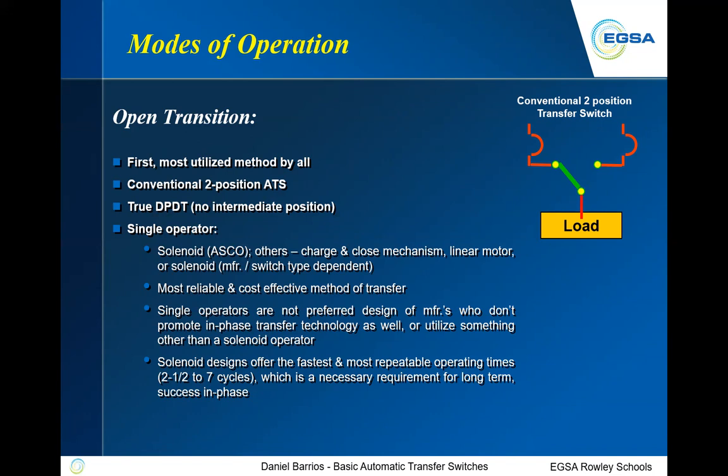A typical open transition switch transferring between utility and a standby generator would prefer to be connected to the utility. What does that mean? That means that should the utility go away, you go to the generator.